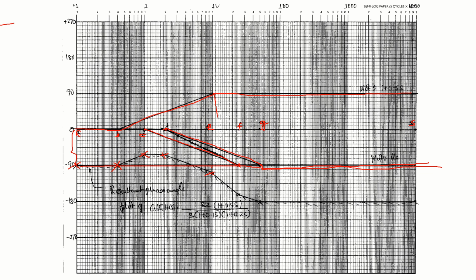Come to F. Right now, this point. Minus 10 of this. Minus 10 of this. Minus 20. Minus 8 of this, 28. Plus 10 of this. So 18. Measure 18 and mark. Come here. Minus 10, minus 10, minus 10, minus 30. Plus 10. So minus 20. Here also minus 20. Then you join all these points by straight lines.